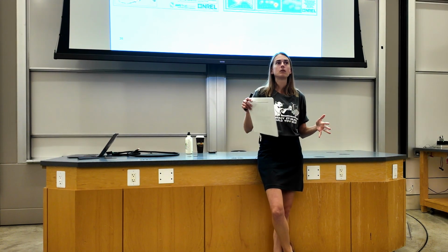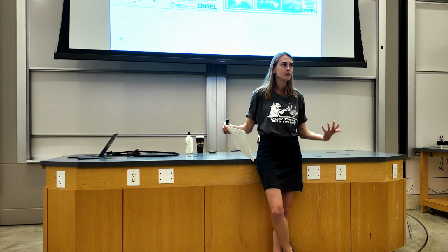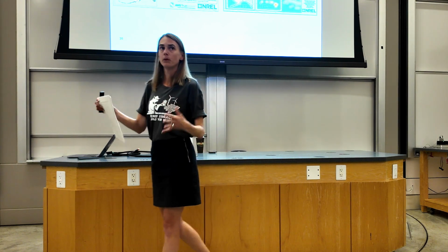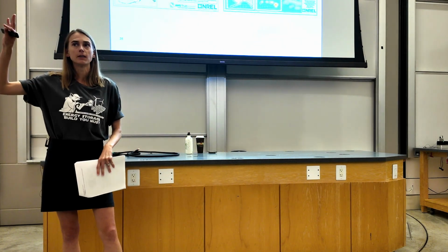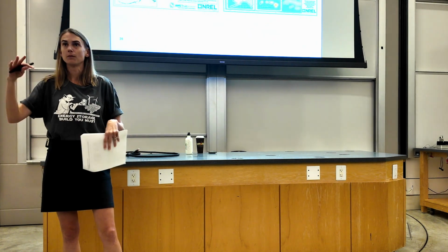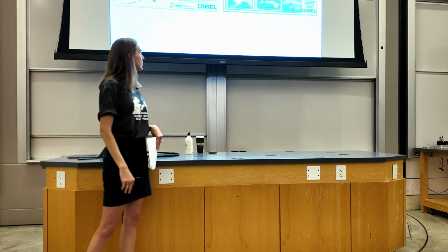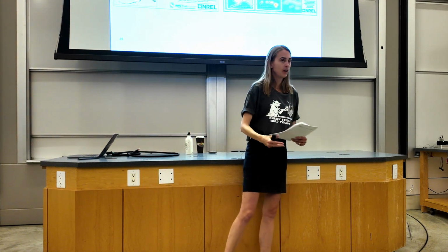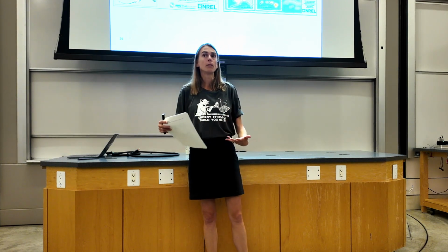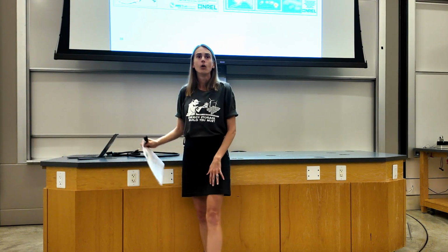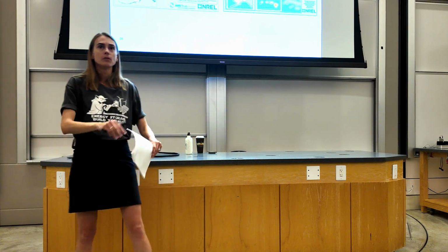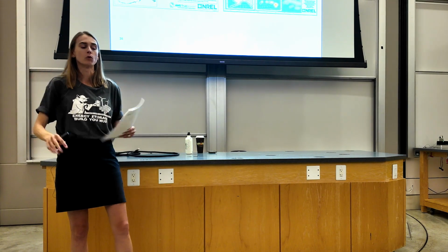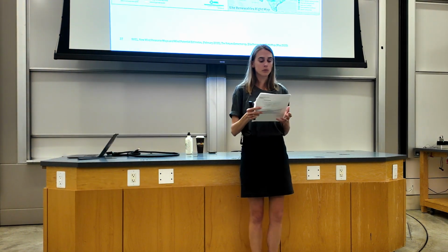But you definitely have to figure out local shading constraints, right? Where, if you're looking at a building, is there a building next to it that might shade it? If you're in the northern hemisphere, like on the southern side in particular, or could a building be built there in the future? Is that likely? Or if you're talking about utility scale ground mount, are there hills nearby? Or do you have a flat enough surface so that the solar panels aren't shading each other at different points of the day?